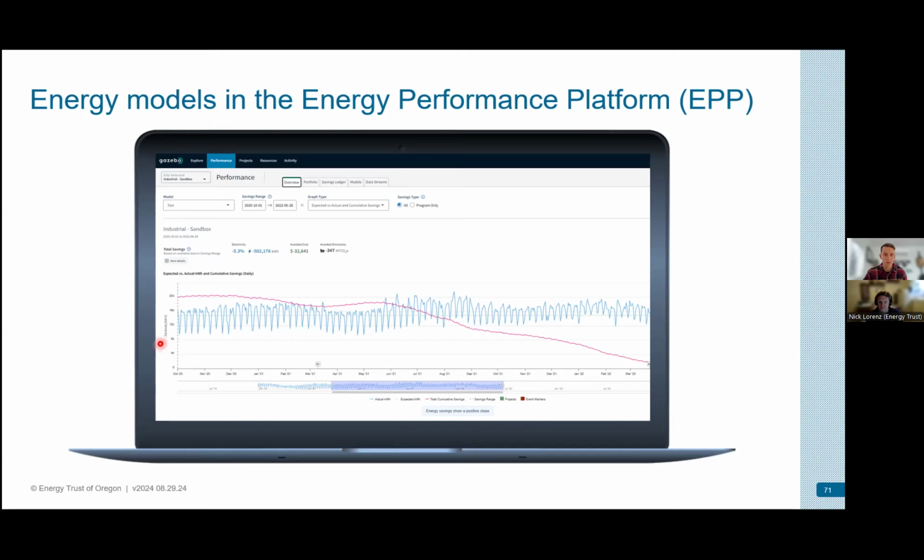So in this case, we've got the blue series hiding back there. That's the actual energy use. It's very challenging to see, but there is the model's prediction shown there as well. The one I really want to call out though is that pink series. That's going to be that energy savings line or that QSUM line. So in this case, for this particular customer, they started off relatively flat and they got on a very slight savings slope, then followed by a little bit of backsliding, and then they really got some projects done. And we saw that QSUM take a nosedive and really indicate strong savings that persisted throughout the rest of the SEM engagement. And this is going to be a key communication tool and a way to check in on energy performance while you're in the SEM program.